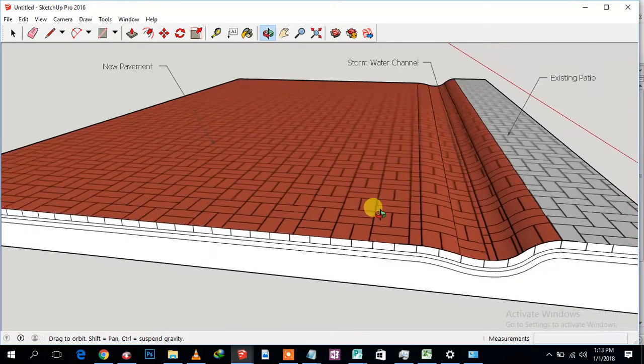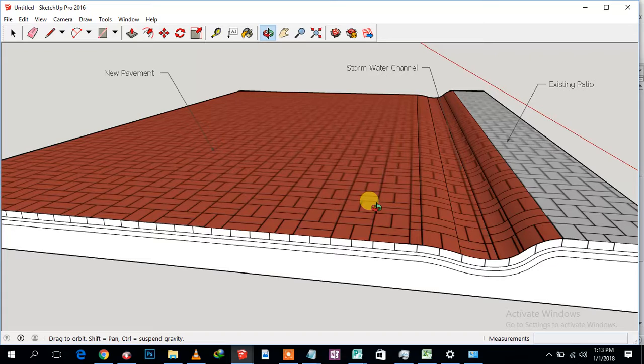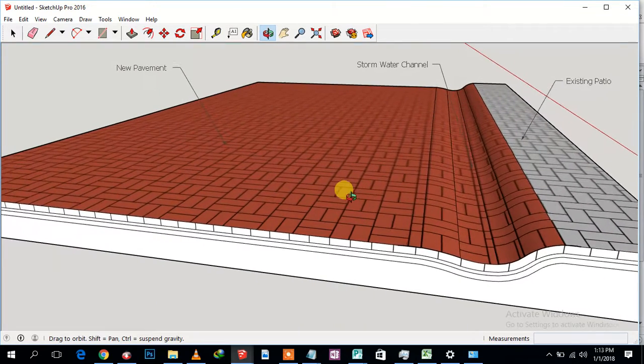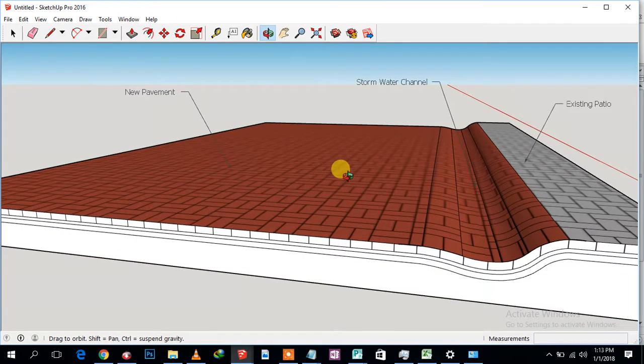On this drawing, I was trying to illustrate, or to stress, that we need to make it as flat as possible, and then our drain system, we should design a U-shaped drain system. This will be the partial. After that we should start to gradually lower it, just to form it like a channel.